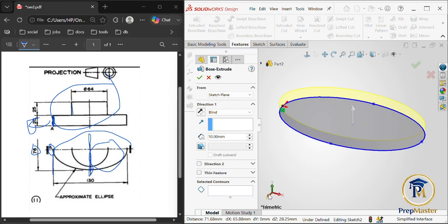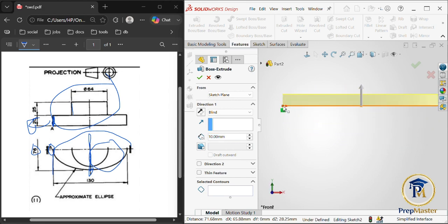If you put the front view up, it's meant to go up like this. Yeah, up, not under. If it's under, it will be like this. This is not what you want. You want this up. So yeah, the extrusion is what, 20. The thickness of the extrusion is 20. So we'll just click on 20 here, then press enter. Yeah, and now we can accept it.